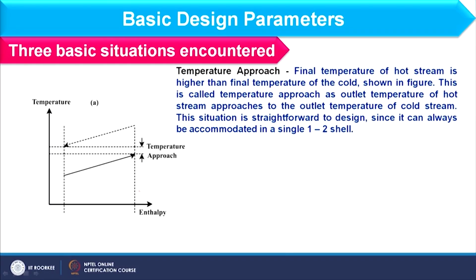You can see temperature approach in this diagram. This is the hot fluid, where there is a temperature decrement, and this is the cold fluid, where there is a temperature increment. Temperature approach is basically the difference between the outlet temperature of the hot fluid and the outlet temperature of the cold fluid.